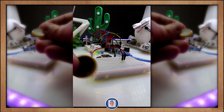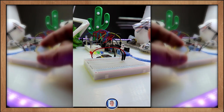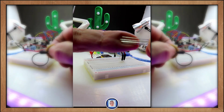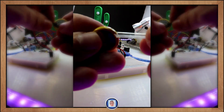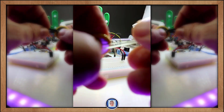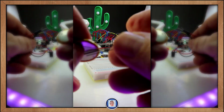It's always good to be sure, and you can verify this with this coin cell, inserting it in between the common pin and another pin. If it doesn't work, we just have to flip the cell around. Let's try this. Sorry for the focus. Okay, since it doesn't work, I flip the cell around, and now when I connect the 2 leads, you can see it turned on. Good.